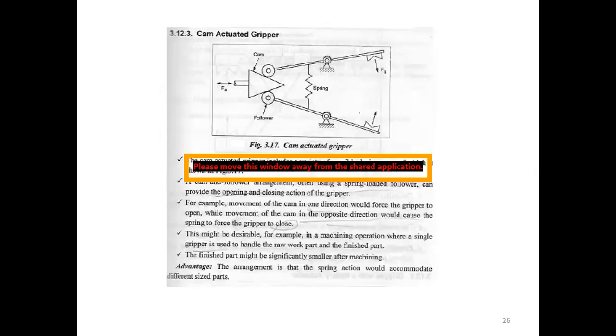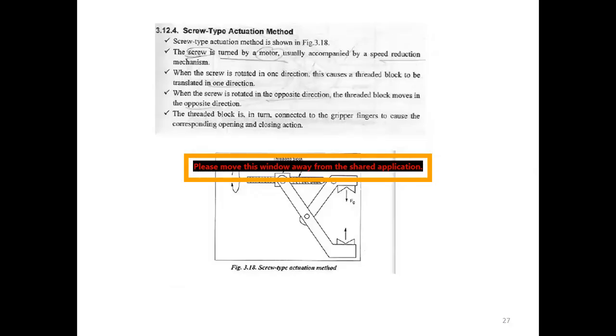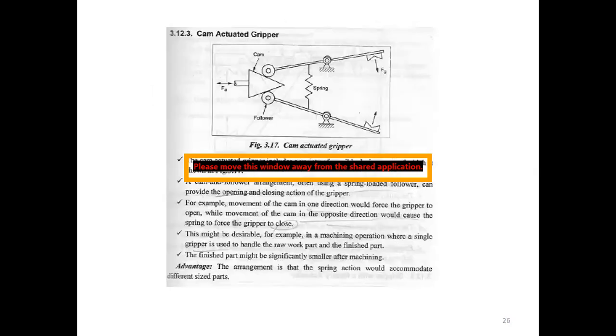The next one is the cam actuated gripper. The cam actuated gripper has a spring-loaded follower, which is used to provide open and close actions of the fingers.